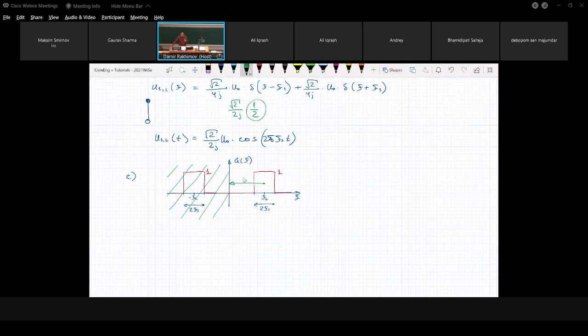But if you go to the low pass range and normalize the transfer function, then you will have 2 normalizations, one for the signal itself and then one for the filter. As a result, energy is smaller than it should be. For this reason, we say don't do normalization for the filter. Do normalization only for the signal.